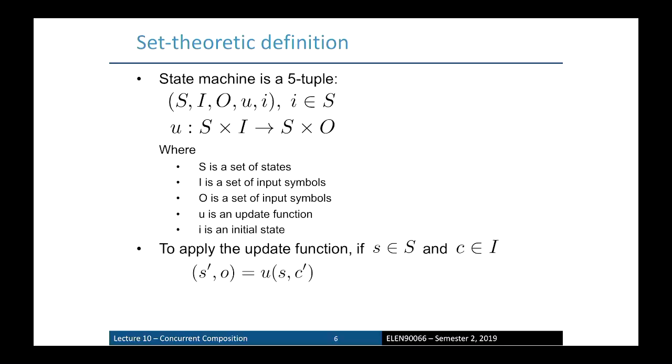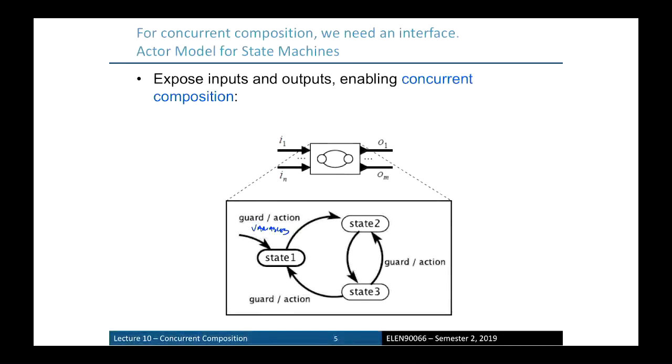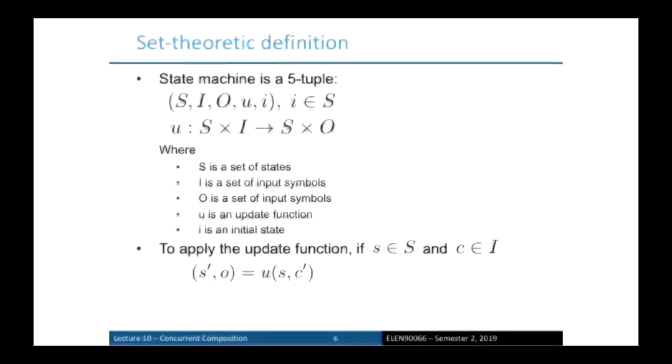We've got a set of states. We've got 3 states here, so we've got a set of states that describe the state machine. We've got a set of input signals. Remember, it's a set. It could be continuous variables. It could be just absent, present, but it's a whole set and multiple inputs of differing types. Likewise, we've got a set of output.